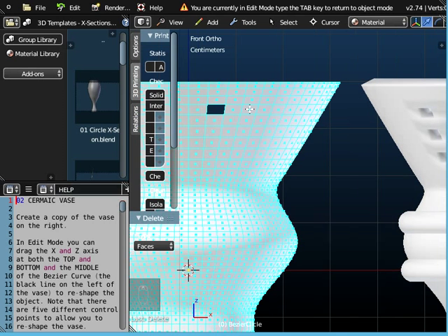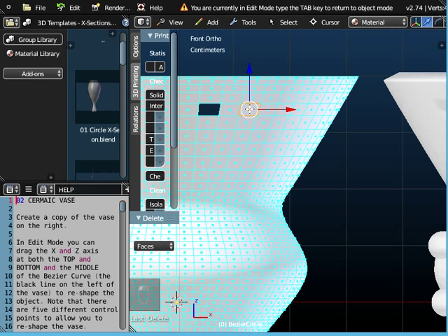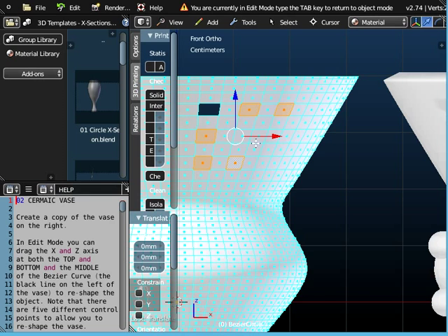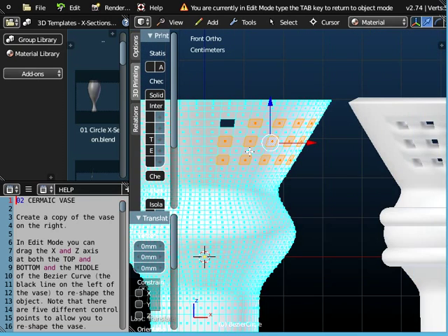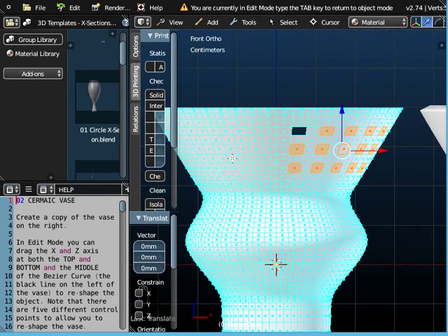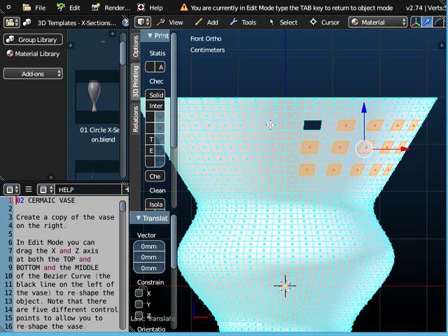and that is if we hold down the shift key on the keyboard, we can select multiple faces at the same time. Now it's not always easy to get all of them in one go, because these crosshairs tend to get in the way. So I was having problems getting that one, so I've just zoomed in. So I've highlighted a bunch of faces there.